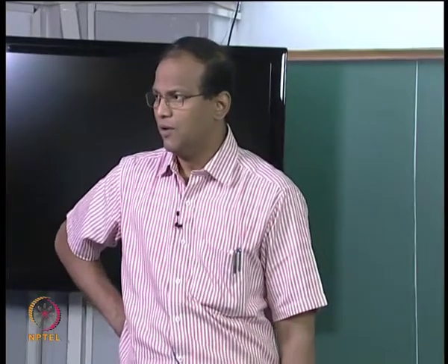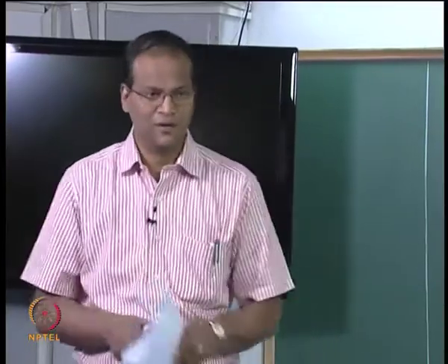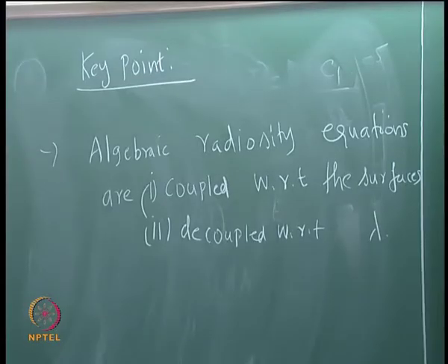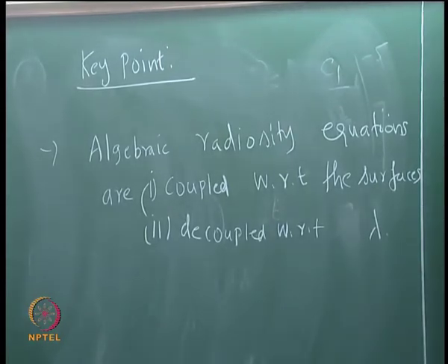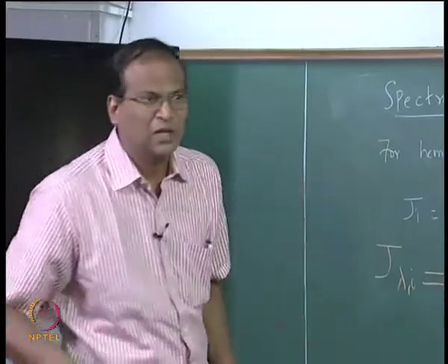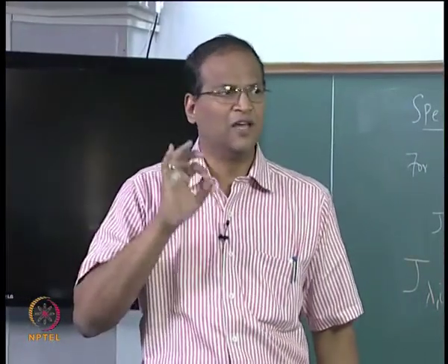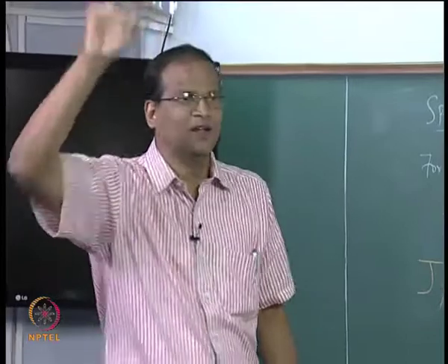That means in n surface equations you will do the same procedure as what you did before, but you have the luxury of doing it wavelength interval after wavelength interval. So you can carry out all these calculations sequentially over various lambdas. Therefore, if epsilon lambda versus lambda is such that no approximation is possible, you will necessarily have to divide it into 100, 200, 300 wavelength intervals. It is computationally very costly. Spectral calculations are very costly. Do not think that only CFD is time consuming.